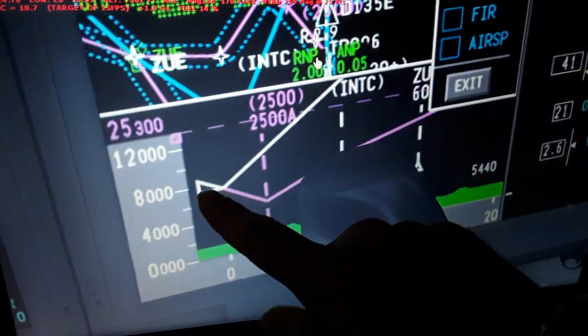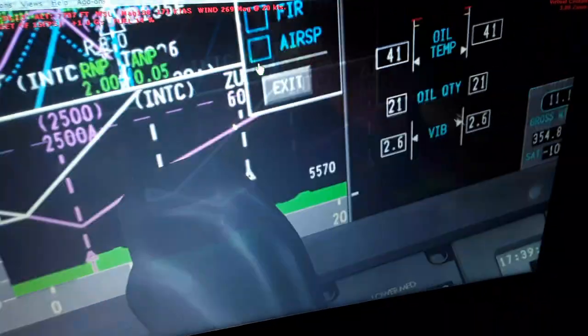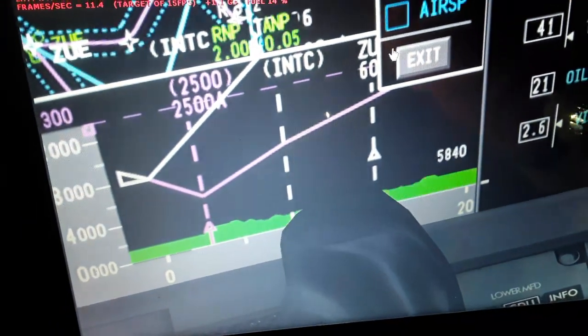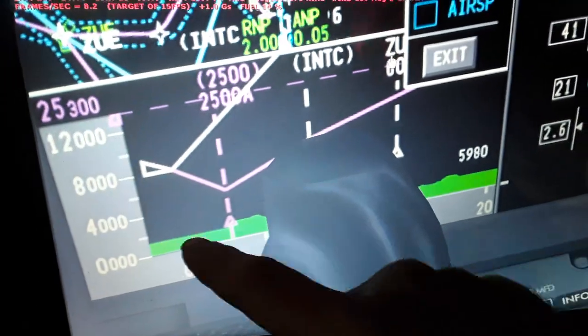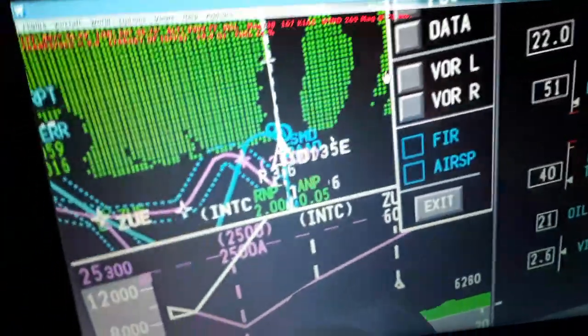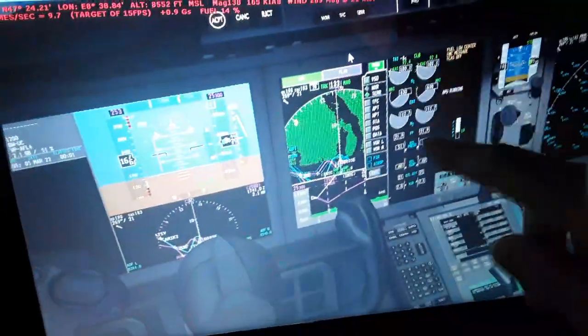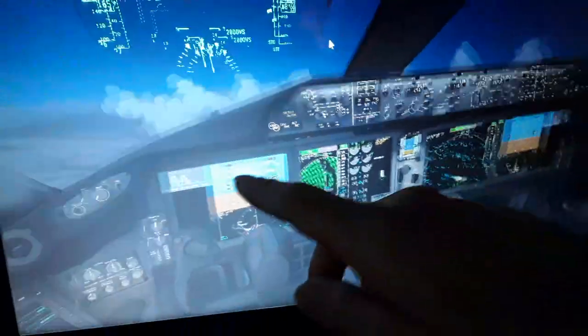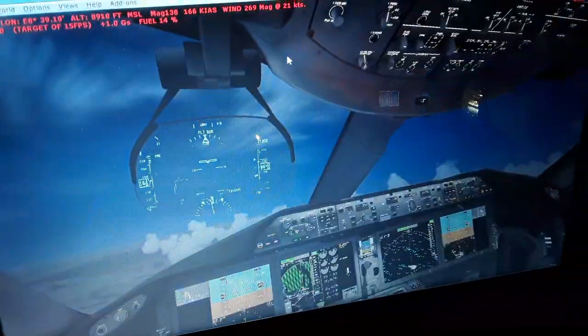The aircraft symbol is here, it's 8,000 feet, this triangle, and the terrain is 5,600, 700. It keeps climbing. This green wave below us, up to 20 nautical miles away. As you can see also around us in the horizontal of the engines, also in the autopilot. Over here the airspeed, all the data that we have.